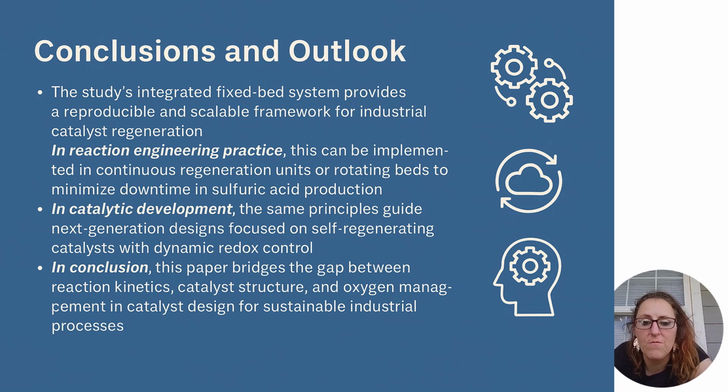Mild oxidative regeneration preserves catalytic structure and redox activity, while air regeneration leads to irreversible degradation. From a reaction engineering and catalytic development standpoint, the findings underscore the importance of coupling kinetic modeling, structural control, and oxygen management in catalyst design for sustainable industrial processes.